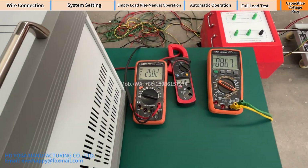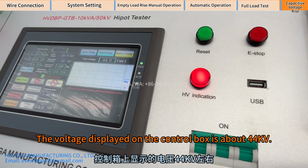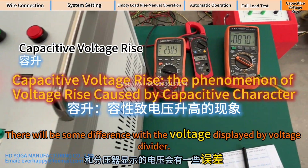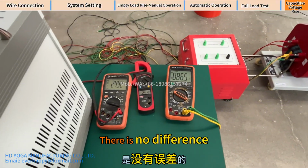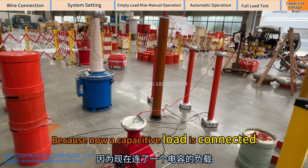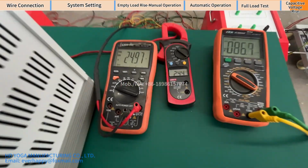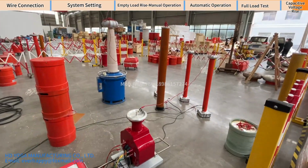Okay, it reaches. With full load, due to capacitive voltage rise, the voltage displayed on the control box is about 44 kV. There will be some difference with the voltage displayed by the voltage divider. When carrying light loads, there is no difference. Because now a capacitive load is connected. The analog simulated load is a fully loaded state. Low voltage current 25A, which is a full load state.